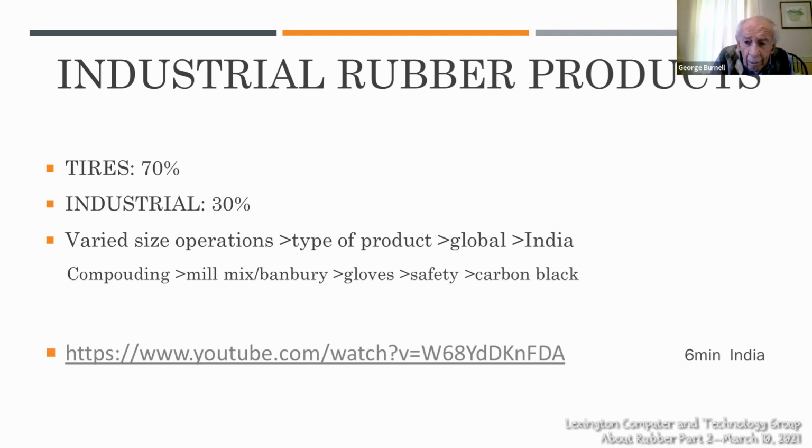One, you have to start with the raw rubber and add your chemicals to it, compound it. So that's mixing the chemicals with the rubber. And then you have to cure it, but between those, it's typical to have the rubber sitting on skids. If they sit there very long, you've got to have them in a refrigerated area. So it gets to be a little complicated.